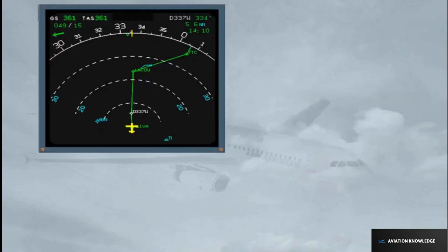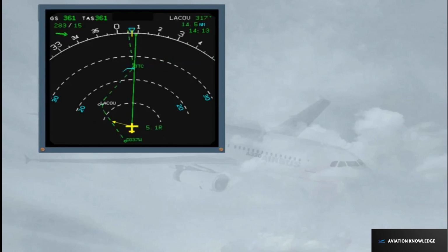Rules regarding predictions. Rule 1. For predictions on time, speed, altitude and fuel, the FMS assumes that the aircraft flies along the flight plan in managed navigation and managed climb or descent modes. If selected heading, track, open climb or vertical speed modes are used, the FMS assumes an immediate return toward the flight plan according to a realistic trajectory. Note, VDEV on the PROG page follows the same assumption.